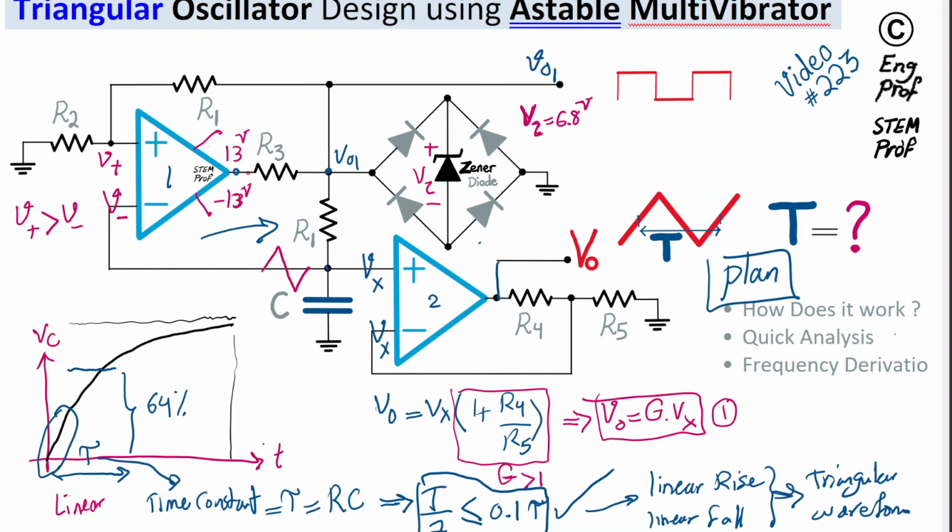It will send a current through this branch, through this diode, down through the reverse biased Zener diode, and then through this diode down to ground. So we have basically this passage available.